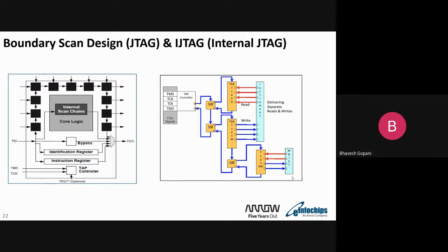There is a certain VCO, right? So the VCO also has some inputs, and those inputs are also connected by TDR. We need to program through the TDR, and there is also a feedback divider circuit. Those we also need to program, at what divider we want. Those kinds of TDR bits we can access directly from outside and program, so the PLL tries to generate the frequency that we need.